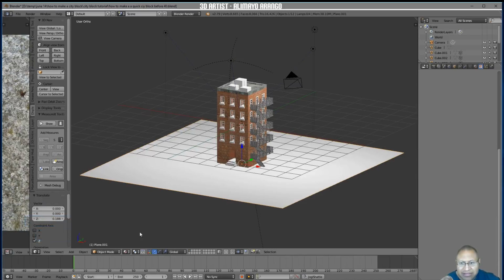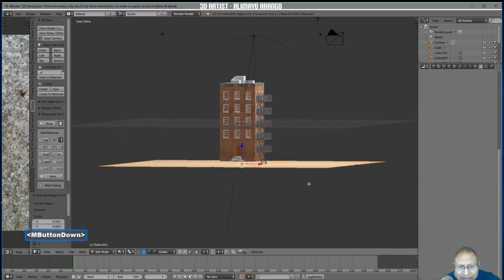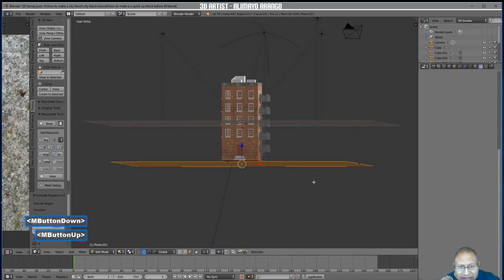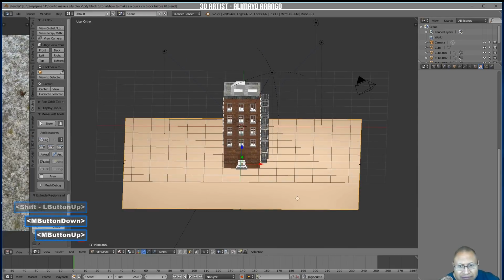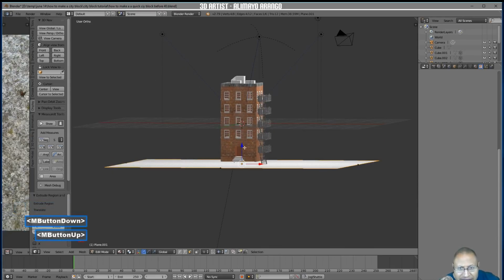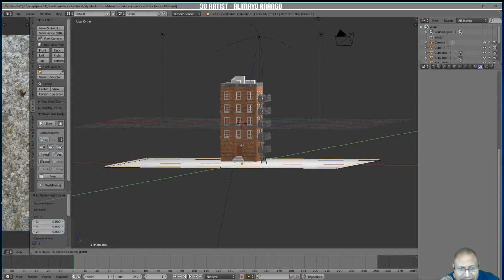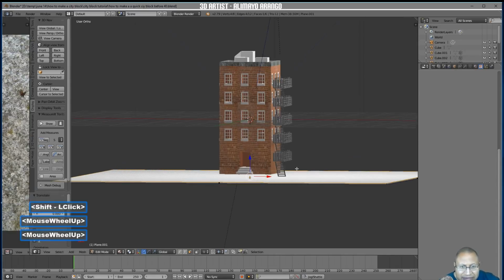So what we're going to do is go to edit mode, press E to extrude, right click. I'm moving this so I can see our plane, so I can see how far I'm going to come up. I'm going to hold shift. Okay, I'm selected on the top now. Now I'm holding shift. Just pull up. Now look at that. You don't want that. So we're going to press G and then Z. Now hold shift, because you want to be straight up and down.